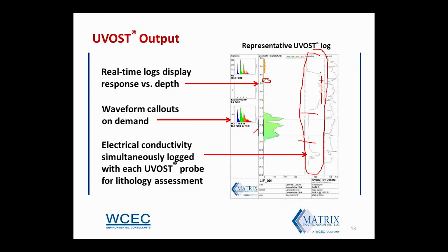We found that it can provide a more objective and complete data set than might be obtained from a typical geological description of a soil sample during a routine site investigation. And then on the far right here, this is basically the rate of push, and that is expressed in inches per second. So down here, if you can see this little scale, that's the 1 inch, that's a ½ inch right here before it. And the idea is to try and push the instrument at an ideal rate of 0.8 inches per second. So this allows us to monitor that rate of push.